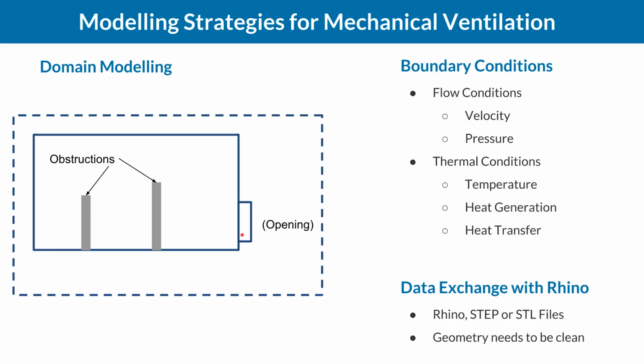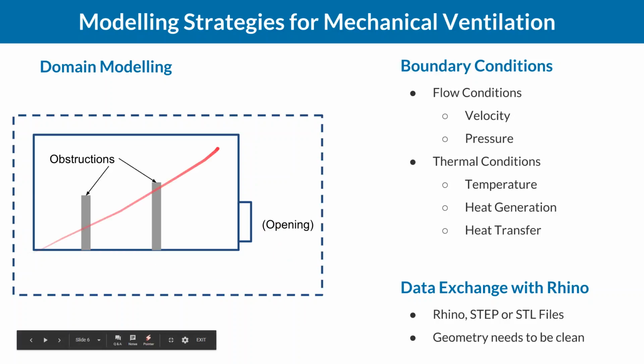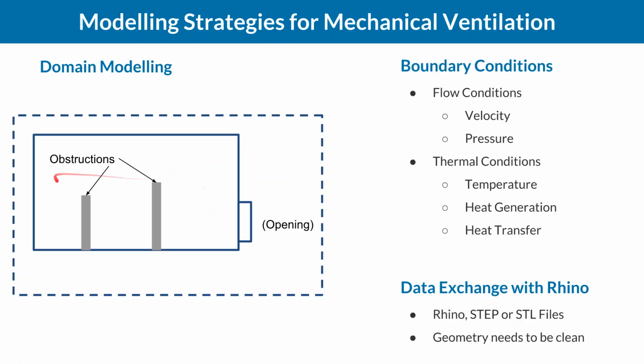And another option is that your simulation can also include external flow only. There you have an additional domain, and then you're not simulating only the volume inside your building, but also the fluid domain around your building. And this can be necessary if you really want to validate a natural ventilation concept which should massively leverage the external flow.